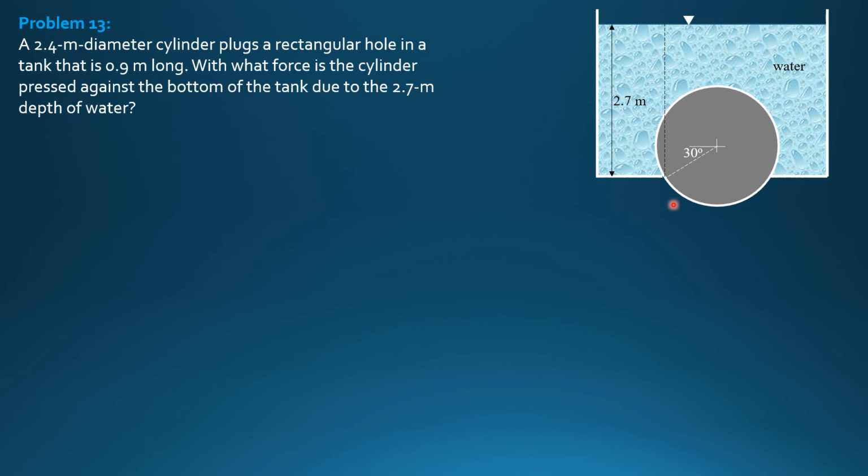So by principle, the FV net would be the volume bounded by the vertical lines to the liquid surface and this curve. So since there are two parts, this is the net area to be considered, and the force is upward. So this is the area to be considered, and we have another area here, so we just double the area later.